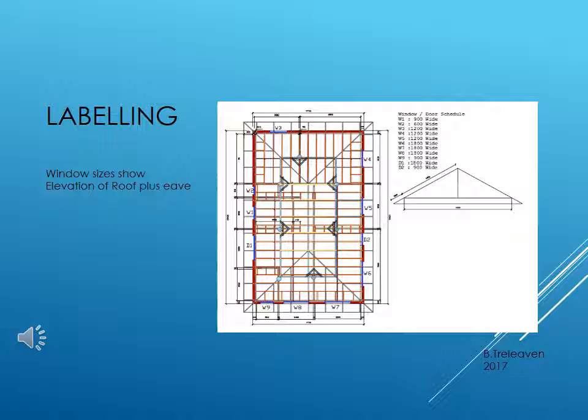You'll also notice on the right hand side I've done an elevation of the roof. It's 30 degrees, and I've also given you the sizes of the span of the rafter, and also the length of the rafter, and also the length of the eaves overhang. And so that will be very valuable for you when you're calculating your timber sizes, because you will be looking at tables where it requires to know what the eave overhang is. I hope this will help you, and now you can put this into practice using your span tables, and you need to use the current ones.